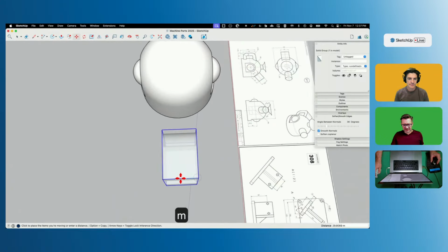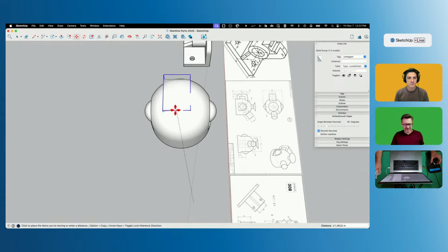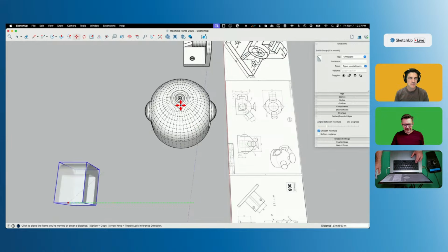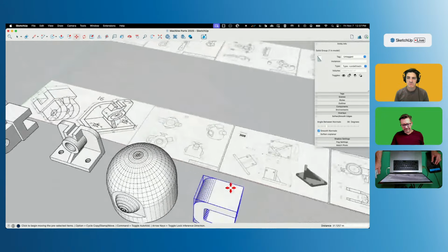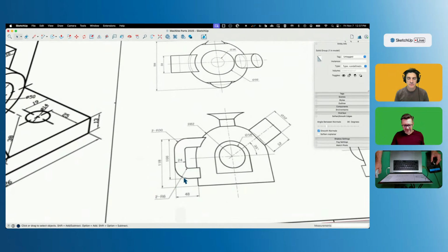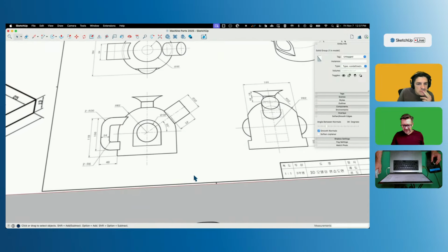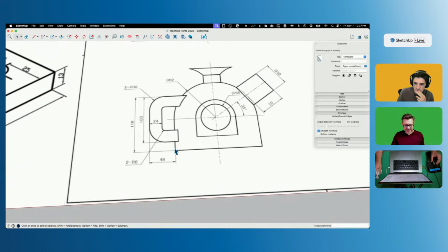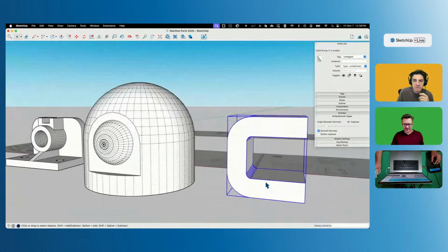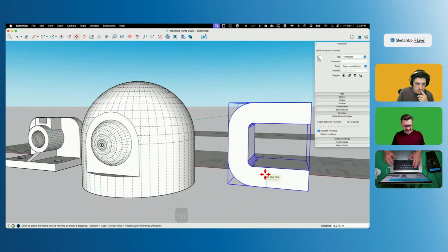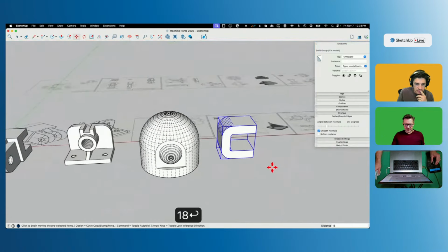So I can get the center here quick enough. But again, to get the center of this, I'm going to have to toggle on my show hidden and then use that right there like that. All right, so we're pretty close. The last thing I want to do here is we got to move it vertically. So vertically, it is at something off the ground. Oh, 18. So 118 minus 100 is 18. So if I move this vertically 18, that's where it needs to be.